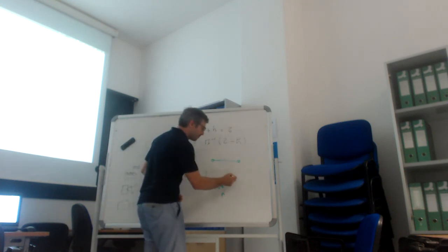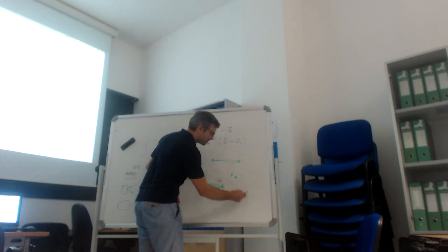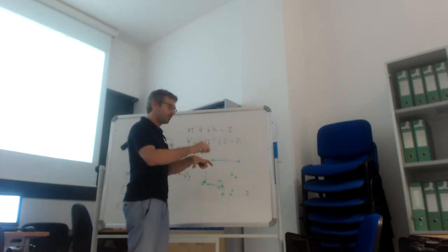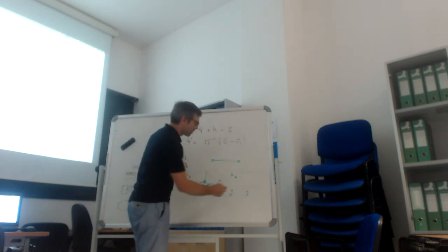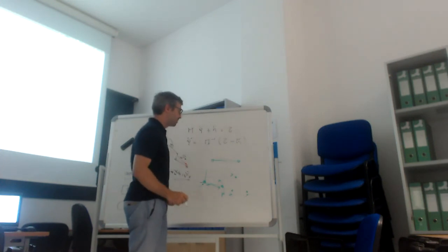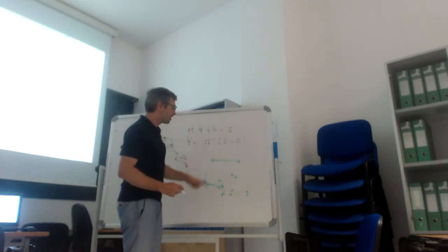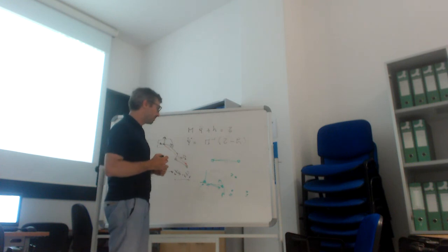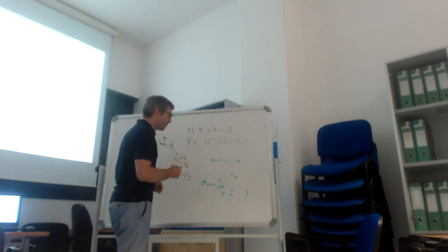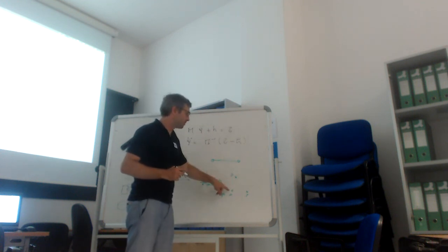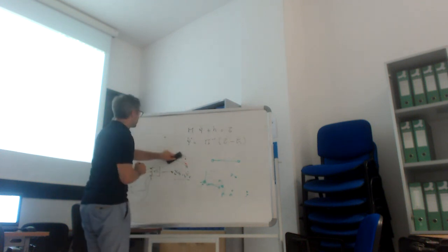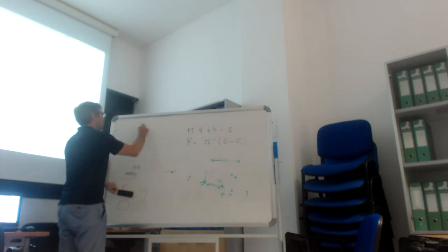Whenever you have three feet, so these three, two constraints, this is only one, because whenever you have two feet, the third one needs only one additional constraint. So with three points on the ground, you get a rank of 6 in the Jacobian, even if the Jacobian has 9 rows, because each foot is adding 3, 3, 3.